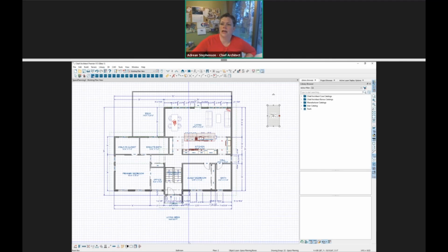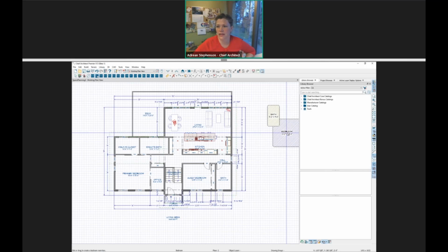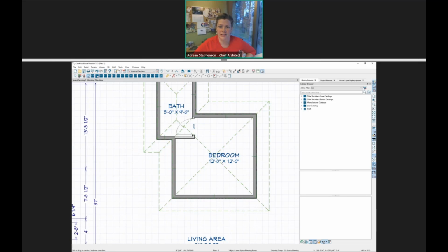I believe you can overlap room boxes in X12 and X13, and if you were to build these, let's just try it really quick, then the program does some of that breaking for you. I don't know if that's helpful or not, but you may just try overlapping your room boxes, and then when you do the build, it should try to come up. That's what I've been doing all these years, and sometimes it's tricky because it doesn't always work the same way every time you build it.